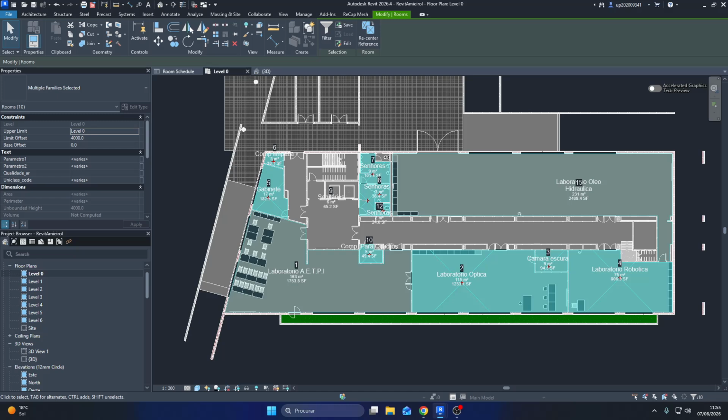High CO2 values may indicate poor ventilation or excessive occupancy. By connecting sensor data to a BIM model, it becomes easier to identify problematic rooms, visualize conditions spatially, and support facility management decisions. In a real project, this workflow could be connected to live sensors or time series databases. In this coursework, the sensor values were simulated, but the logic of the workflow remains the same.